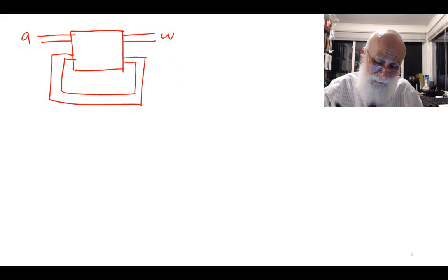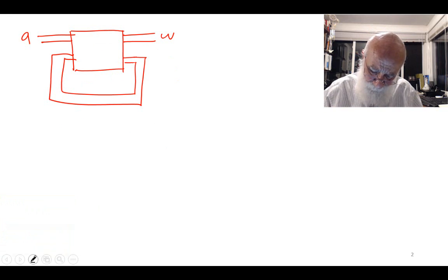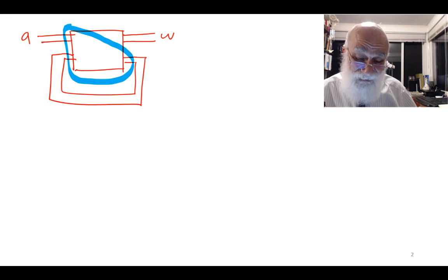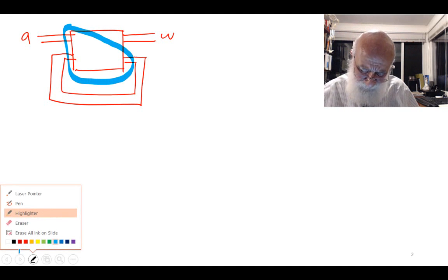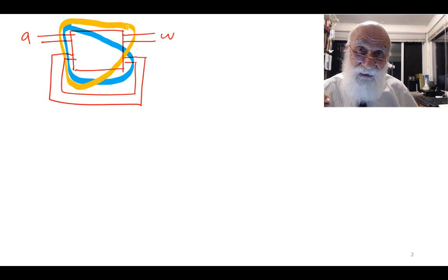So the circuit has a function in terms of the present state and the input, which decides on the next state of the circuit, and it also has another function which decides on the output of the circuit based on the present state and the input of the circuit.